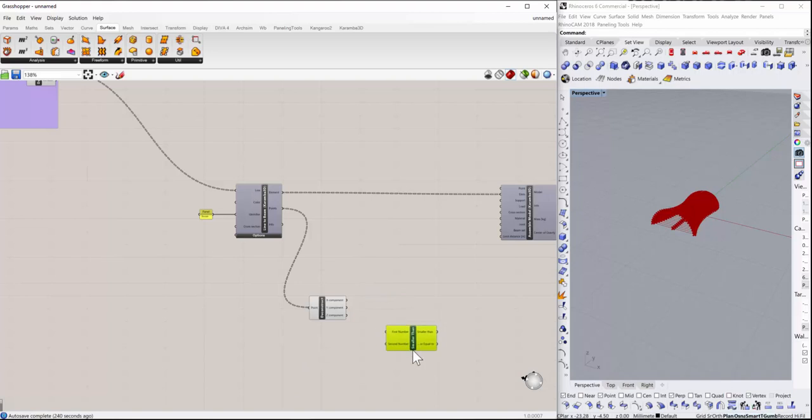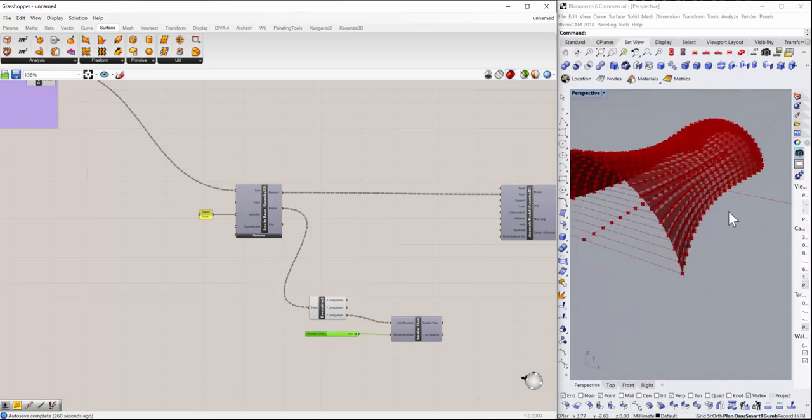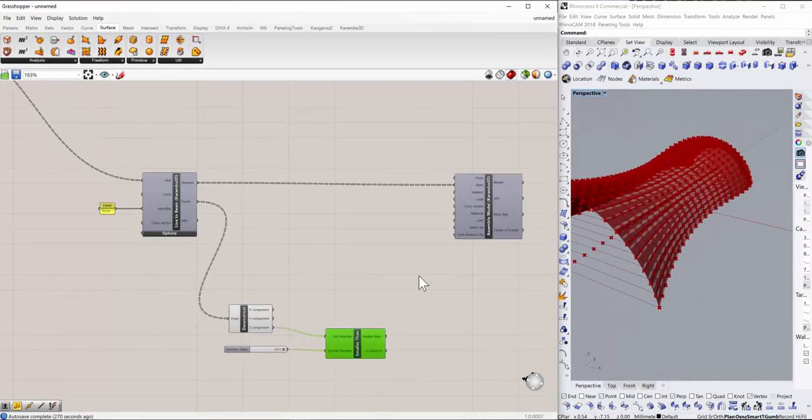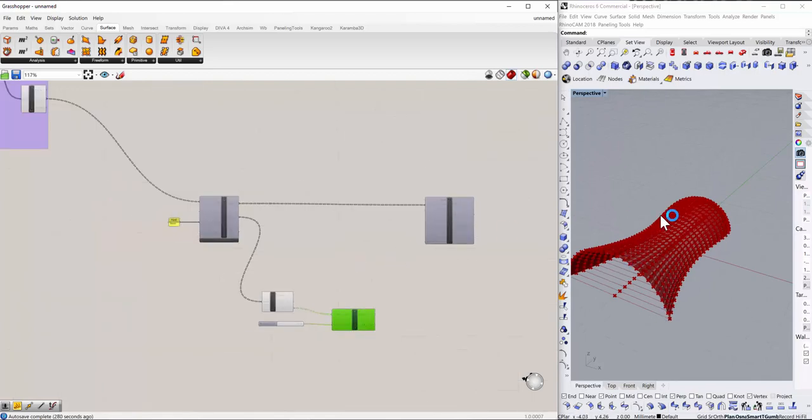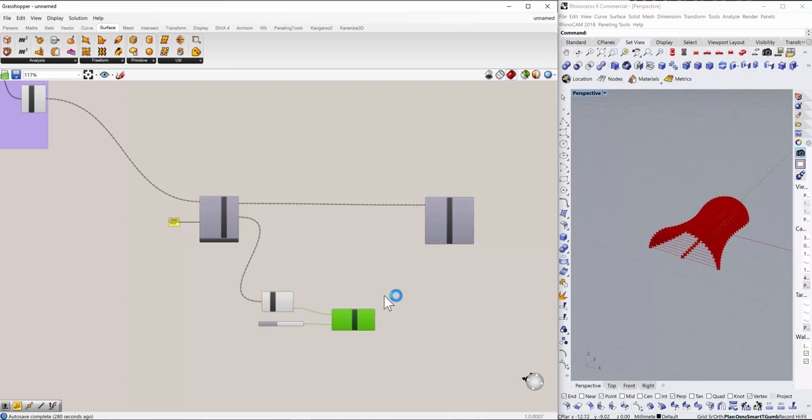So if the value of the z, that is the vertical height, so value of z is less than say 0.01, so all the points at the bottom are at 0, creating support. So all the bottom points will be acting as support for this surface.